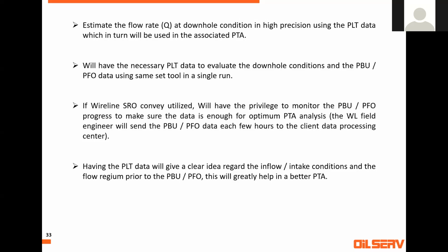Okay, having a PLT run before PBU or PFO will give a clear idea about the downhole inflow or intake condition. Are you producing from a single perf zone? Are all the perf zones producing? What is the rate of each layer? What is the intake of each layer? Are you injecting in a single meter and creating some kind of fracture?